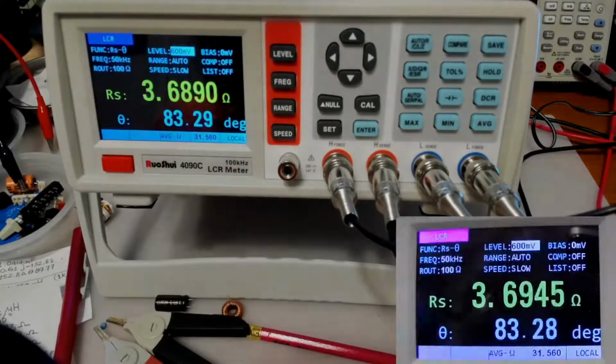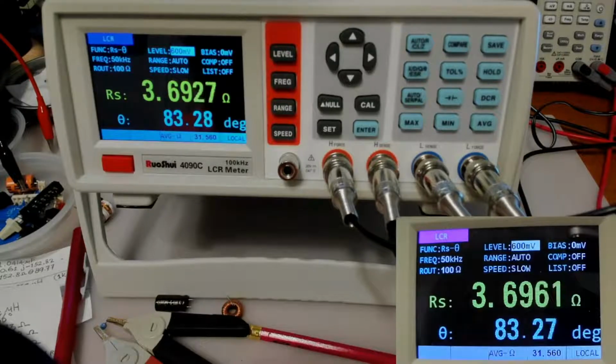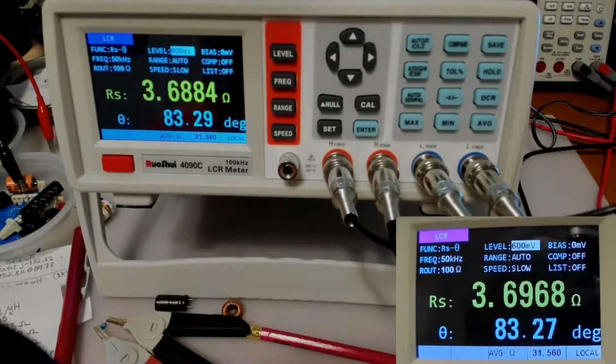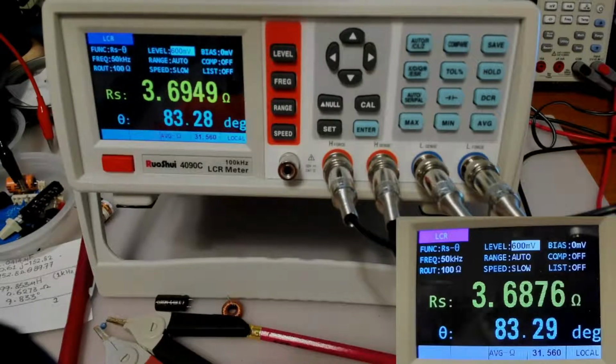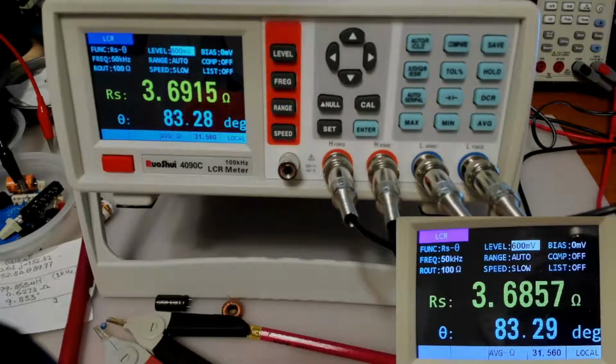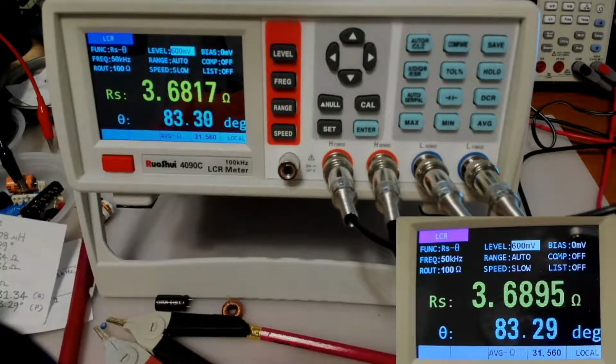So I remember when I was going to college and we had to do these calculations on AC circuits. If I had to multiply or divide them, I would go to polar notation and apply the multiplication or division, because that's easy. And then if I had to add or subtract them, I would go to rectangular and then add and subtract those. Okay, so I hope that was understandable. The polar and rectangular notation in AC circuits actually shows you how the component behaves.